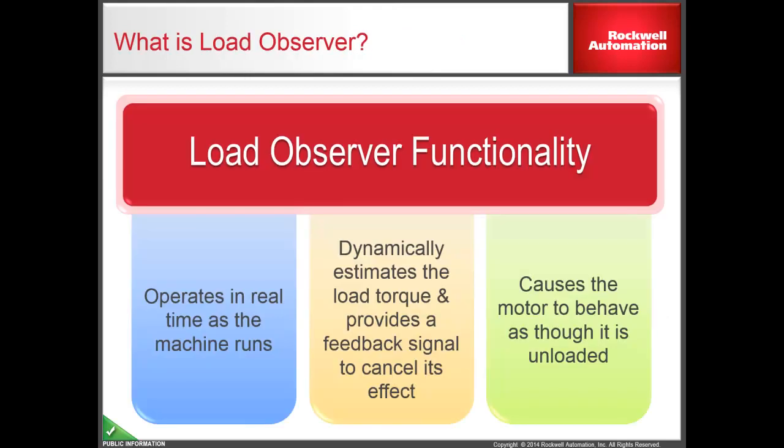When the Load Observer function is enabled, it operates in real time while the machine runs. During machine operation, the Load Observer function estimates the torque required to move the mechanical load and provides a feedback signal to cancel its effect. The result is that the motor behaves as though it is unloaded, which is easy to control.